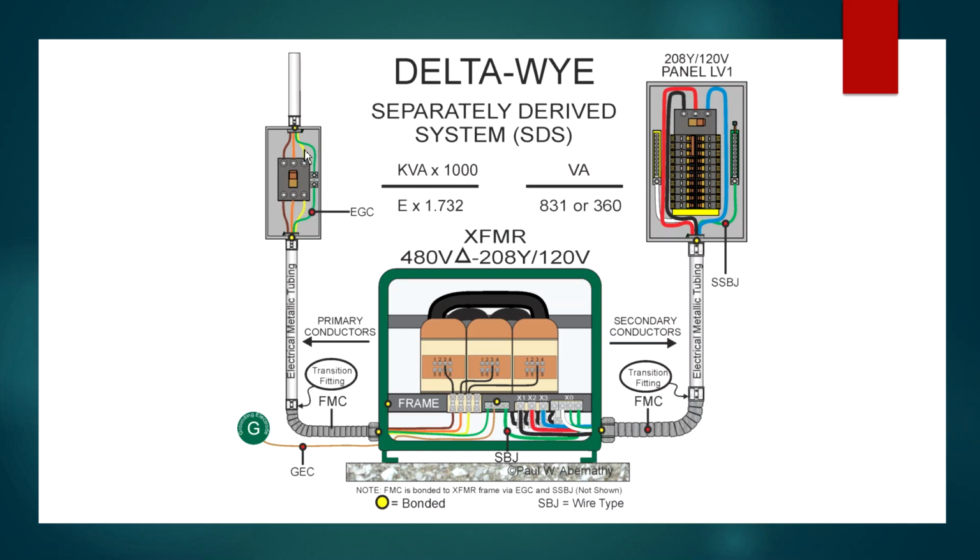Now, what if we were sizing this for an exam, and we're not going to deal with conductors in this episode. We're going to show that later. But what if we were sizing this based on 450.3(B)? And we already know what the primary current rating is. That was 90 amperes for our application, okay? 90 amps. So now let's go back to the code and see what it says. What is the maximum overcurrent protection that we would have here? Okay, so let's go to the code.